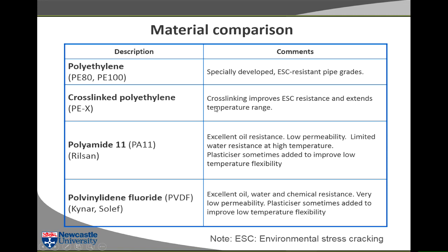And I mentioned this thing called ESC, which stands for Environmental Stress Cracking. I'm going to talk about that later. But environmental stress cracking is a little bit like stress corrosion cracking in steels. It's a form of crack growth in the material which is induced.